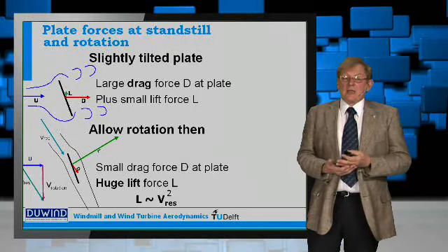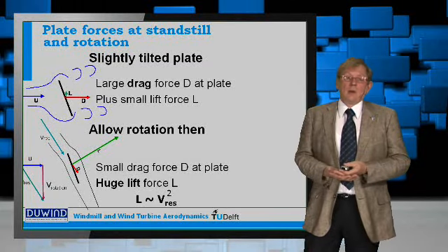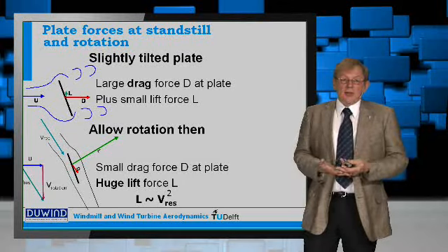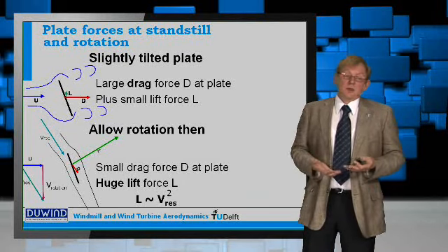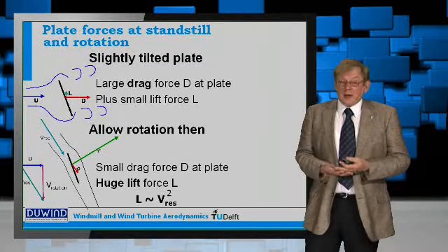Because this lift is proportional to the square of this velocity. So that means, for example, that if your blades are rotating with a speed which is 5 times as fast as the wind, you end up with a force which is 25 times more.